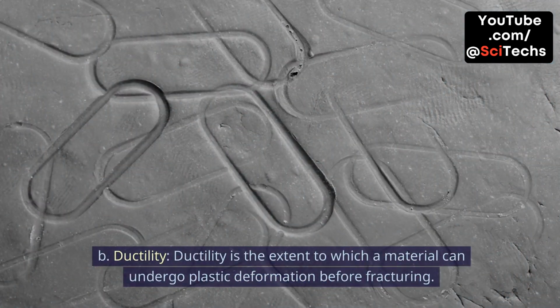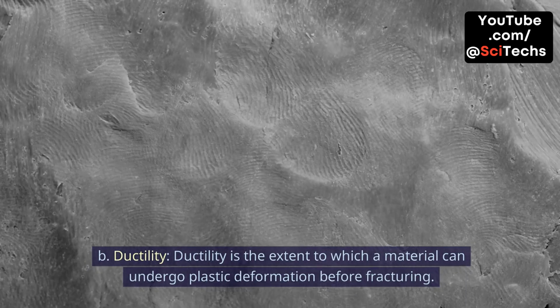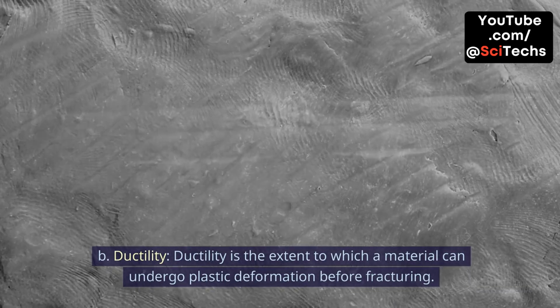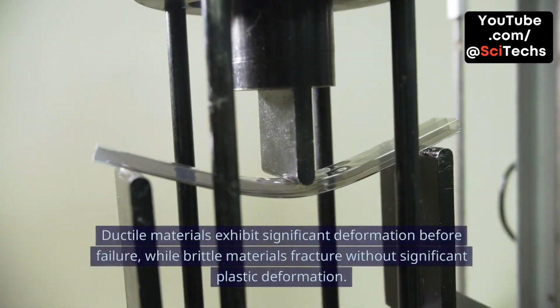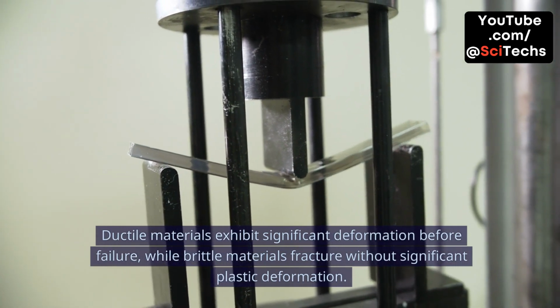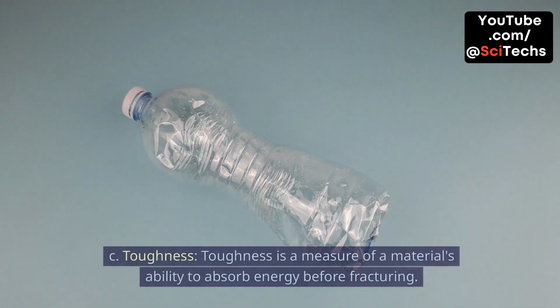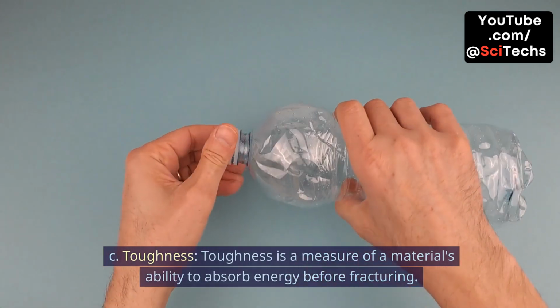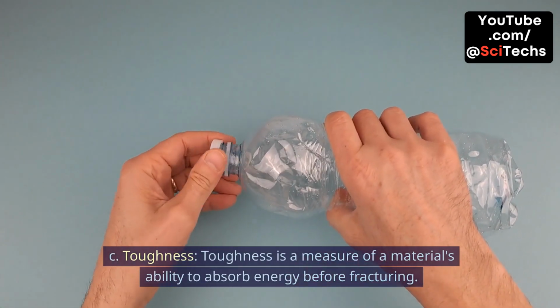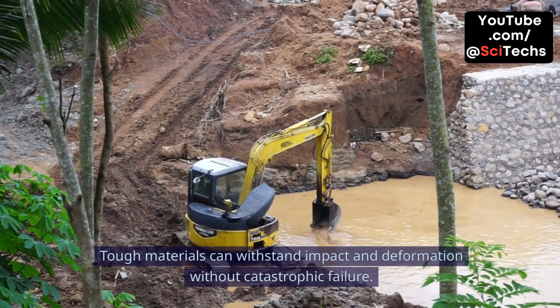B. Ductility. Ductility is the extent to which a material can undergo plastic deformation before fracturing. Ductile materials exhibit significant deformation before failure, while brittle materials fracture without significant plastic deformation. C. Toughness. Toughness is a measure of a material's ability to absorb energy before fracturing. Tough materials can withstand impact and deformation without catastrophic failure.